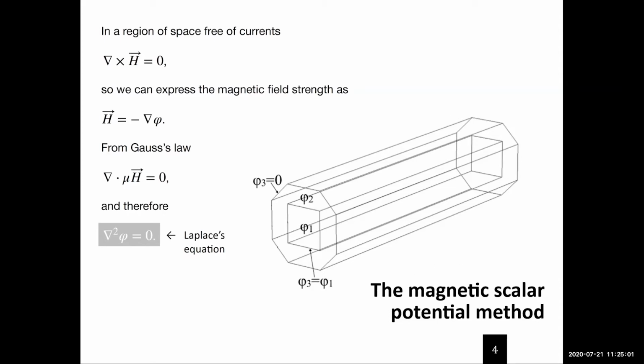So we can use finite element methods to solve the Laplace equations for these two regions. Also, since we need to have the neutron guide inside, ideally we cannot have windings in the inner region. So we can divert this scalar potential to the outer region, establishing these boundary conditions.